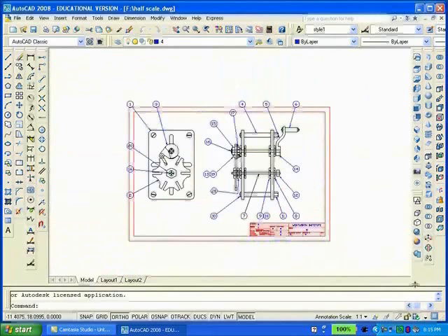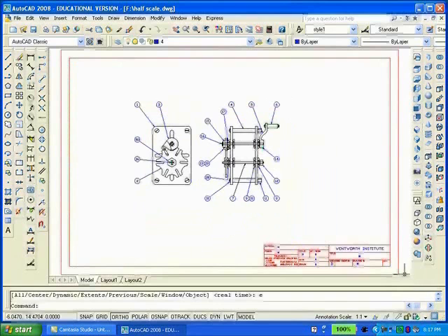And if the format is inserted at full size 1:1, the drawing would appear to be too large to fit on the format, as is shown. As a consequence, the B-size format has to be inserted at twice its size in order for the drawing to fit properly. It is necessary to scale the format to double its size. Now the drawing can be properly plotted.